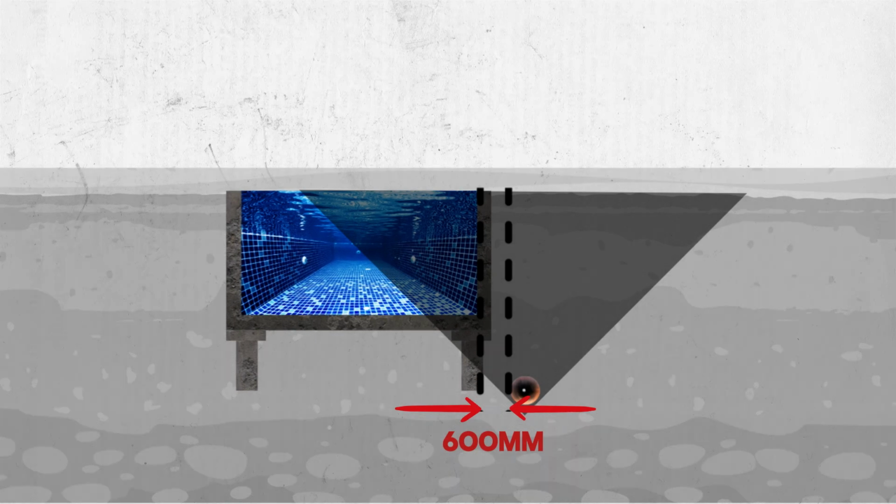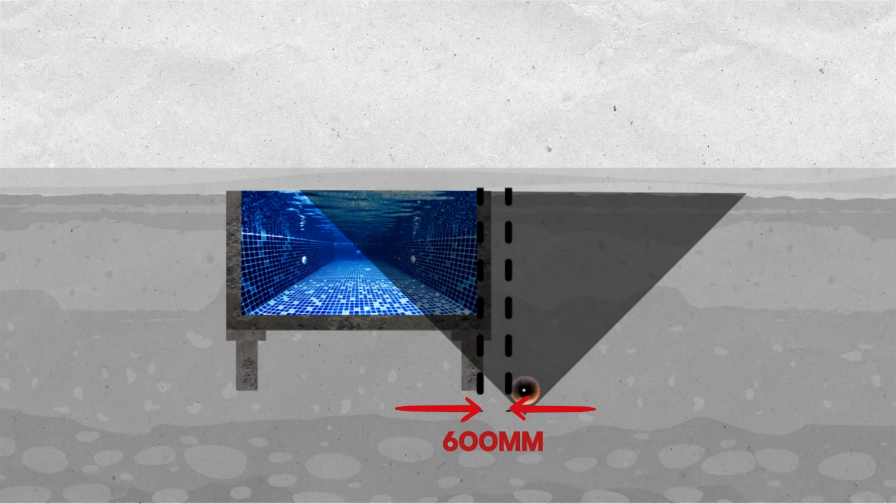When building within the pipe's zone of influence, any footings must remain at least 600mm from the edge of the pipe. This minimum gap, along with a raft of other rules, are set out in the technical guidelines for building over or adjacent to pipes.